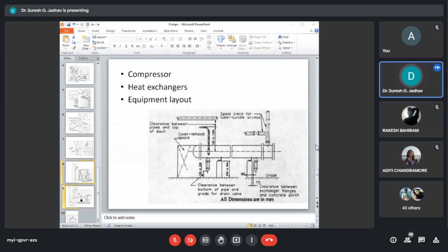Damper design is highly specialized and manufacturer recommendation should be followed. Nozzle velocity at inlets and outlets is limited to 15 meters per second. While planning the layout, provision should be made for this kind of arrangement to consider in the complex.